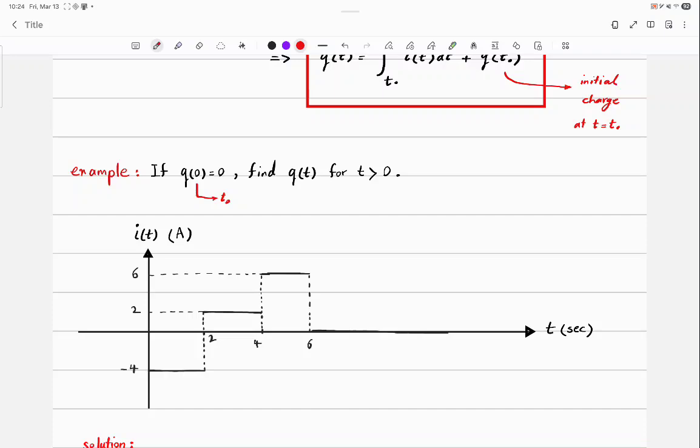Or the other way. If you're talking about supplied power, for example, you're talking about some projector, okay? And you want to calculate its supplied power, and you get negative 100 watts. What does it mean? It means that it's not supplying power, it's absorbing 100 watts, but it's not supplying, okay? So remember, these are negative of each other. So let's do an example. I hope that clears everything.